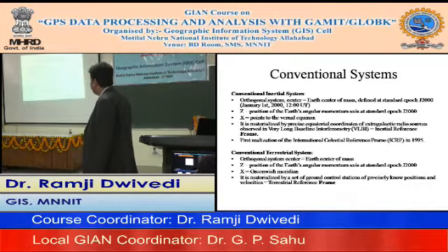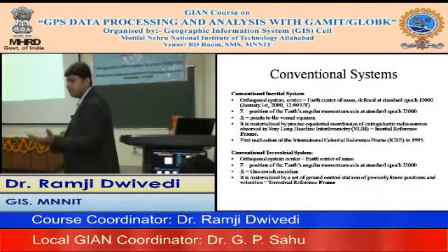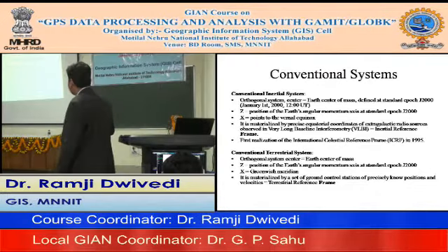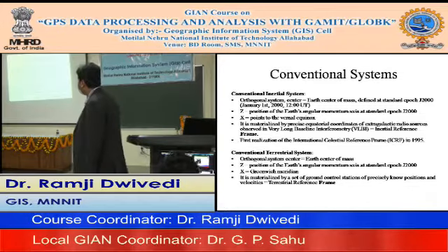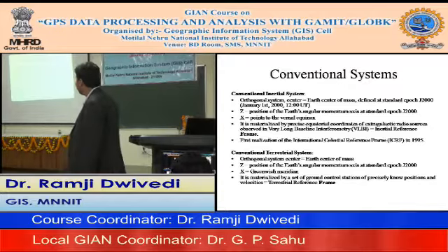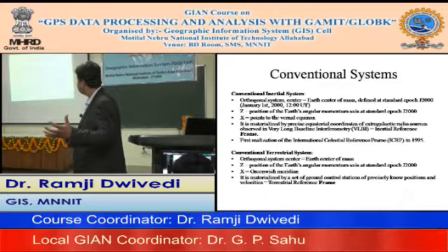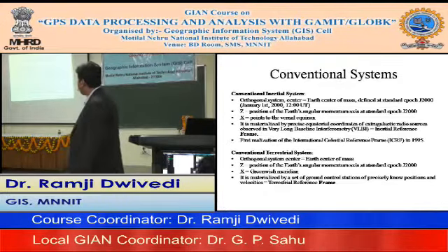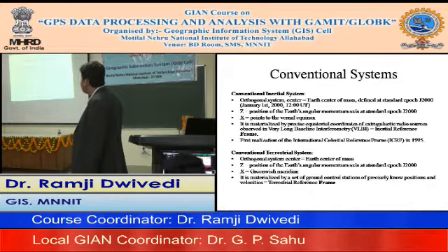So the first realization by the international body, the so-called IERS, was in 1995. Then similarly we have a conventional terrestrial system, and it is materialized by a set of ground control points of precisely known position and velocity, which establishes the TRF. And obviously the frame is associated with the conventional inertial system also, and it is materialized by precise equatorial coordinates of extragalactic radio sources.